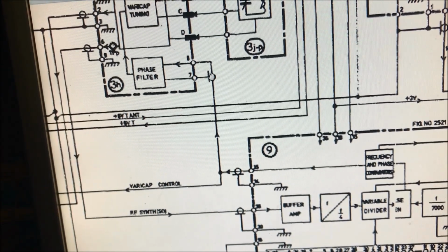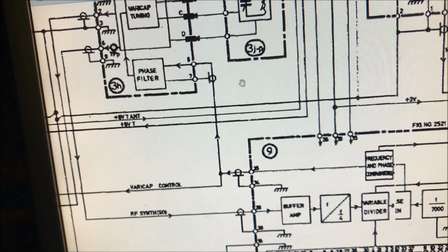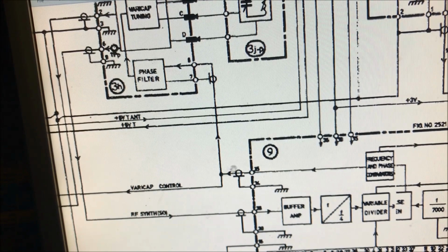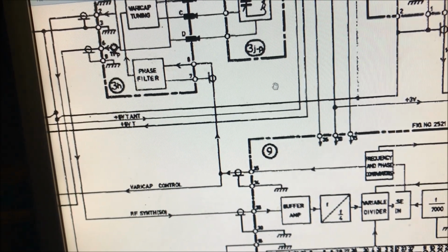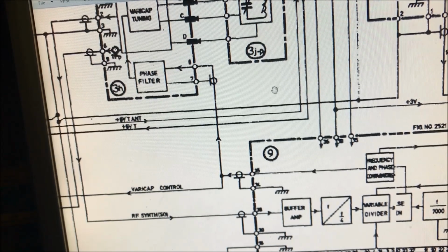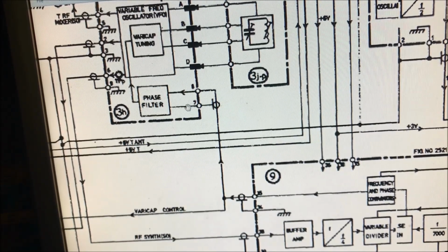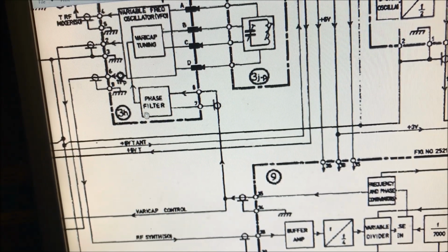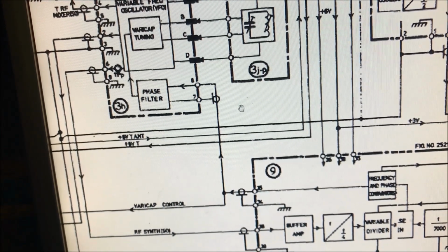Again, I'm going to check the voltage that's being supplied up here, and it'll be around 14.5, 15 volts. And then I'm going to disconnect the wire and apply a separate DC smooth supply to the 3H board. In other words, the 3H board is going to be looking at a separate DC supply for that frequency. Now, here's the telling part.